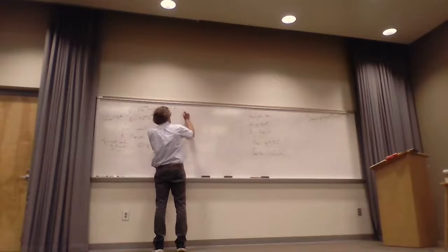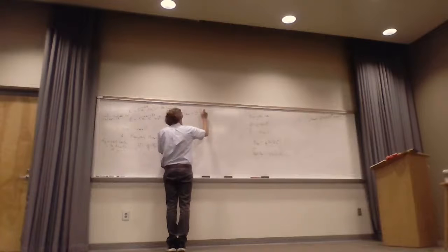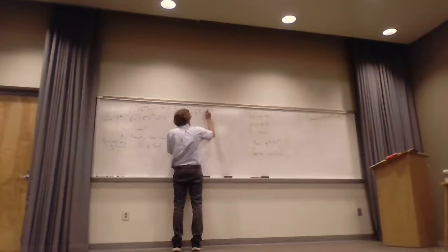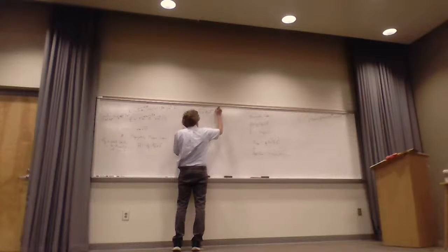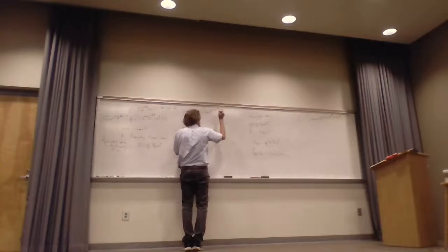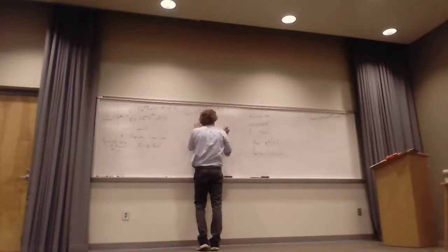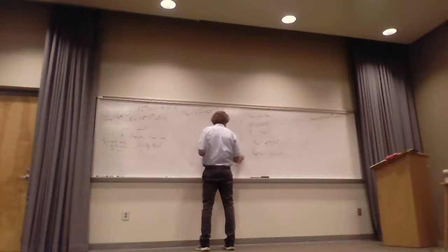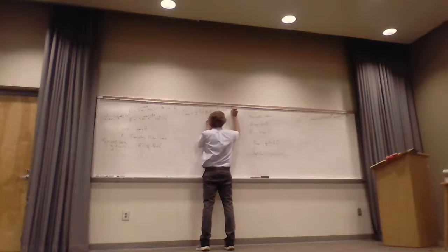Average power, this is in your book, by the way, is 1/2 the real part of E naught e to the minus alpha Z, e to the minus j beta Z, that's a minus, all right, AX crossed into, and this is going to be conjugated, so it's going to be E naught over magnitude of the intrinsic impedance, e to the minus alpha Z, e to the minus j beta Z here.